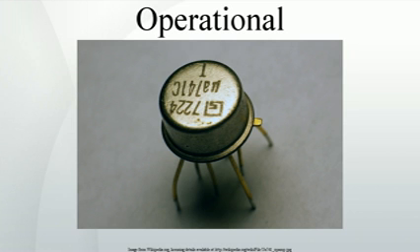This portion of the op-amp cleverly changes a differential signal at the op-amp inputs to a single-ended signal at the base of Q15, and in a way that avoids wastefully discarding the signal in either leg. To see how, notice that a small negative change in voltage at the inverting input, Q2 base, drives it out of conduction, and this incremental decrease in current passes directly from Q4 collector to its emitter, resulting in a decrease in base drive for Q15.